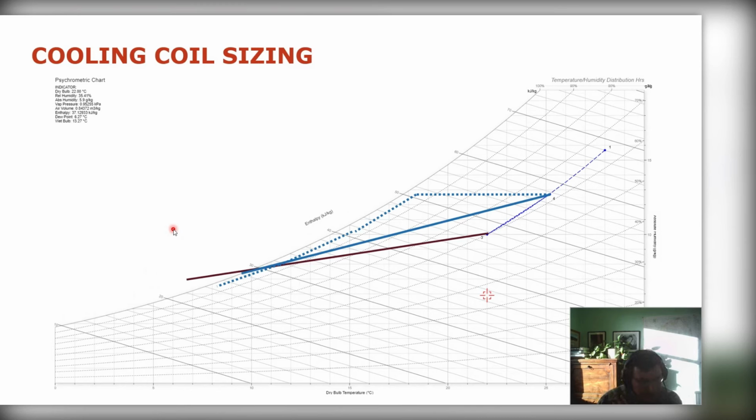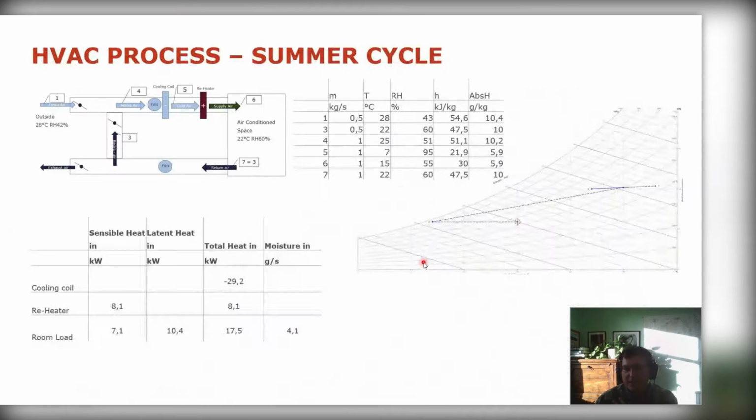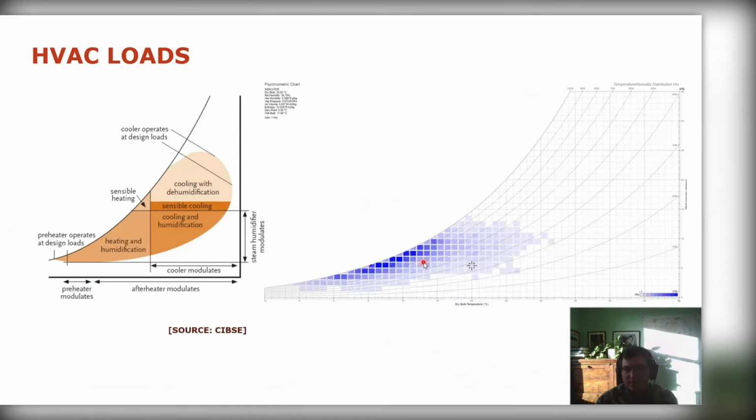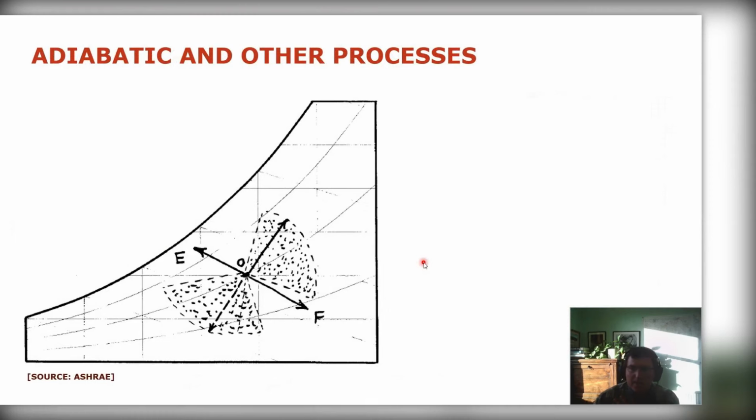And then I think there was a question from John. For evaporative cooling, which line do we follow diagonally up to the left? So for evaporative cooling, yes, it's this one here. I'll just quickly click back to it. Yeah, so evaporative cooling is this one, basically it's an adiabatic line. So that's what tends to happen.